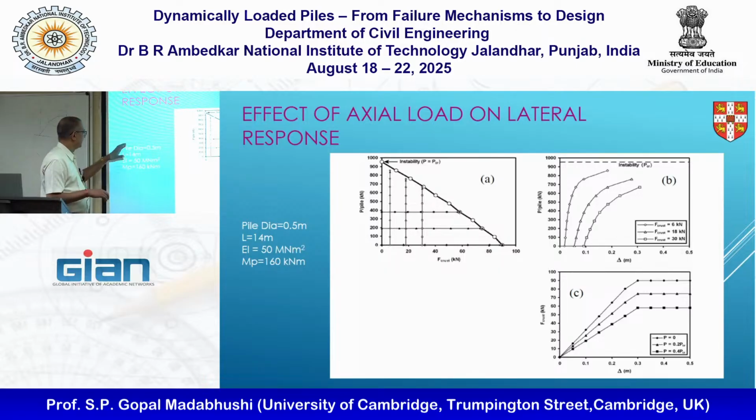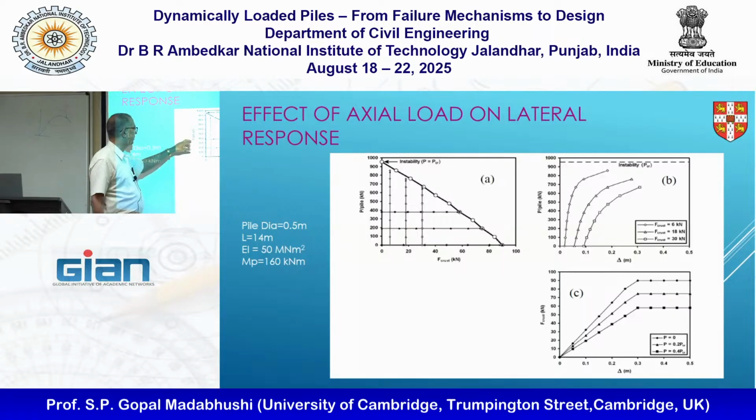Okay, these are the values. So here we are looking at the load per pile. This depends on whether you've got a 2 by 2 pile group, 2 by 3 pile group, whatever it is; you work out the load that the group is carrying, and then the load per pile.